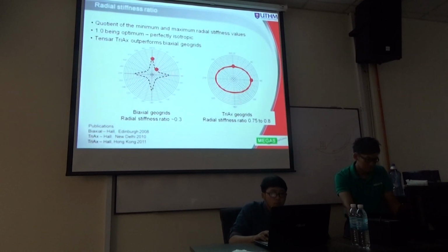When we put all the radial stiffness onto this chart and plot it, this is the machine direction. It has better stiffness: when the number of passes over the settlement is more, the stiffness over the deformation is better, so it has a higher radial stiffness. This is 45 degrees, and this is the 90 degree. Plotting every angle gives a star-like graph. When we plot the same for this triaxial geogrid, it is almost circular in terms of its stiffness in different angles.